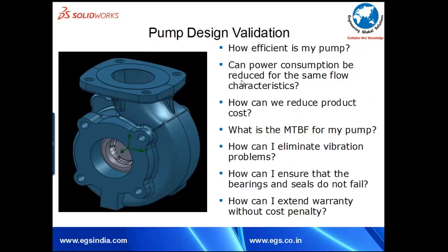As I said earlier, pump design validation as well. When we are looking at the pump design validation, we are looking at the mean time between failures in the pump, and we are looking at how to ensure that the bearings and the seals do not fail. If the bearings and the seal fail, did the seal failure lead to the bearing failure, or did the bearing failure lead to the seal failure? It's a question of the chicken or the egg. This comes in because of the design for life calculations. And the last one is increasing the warranty, which every customer demands without a cost penalty.